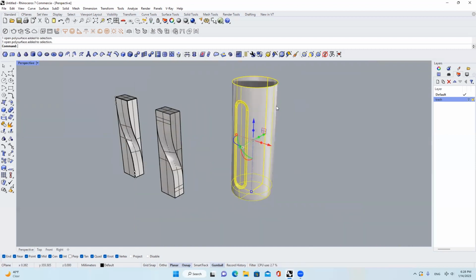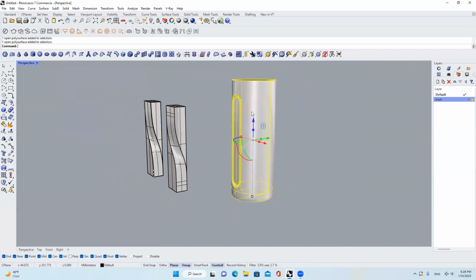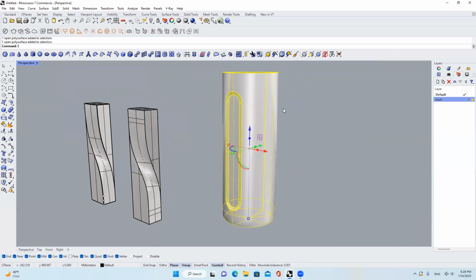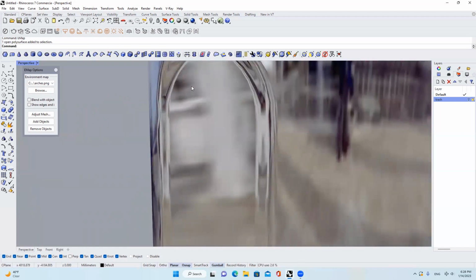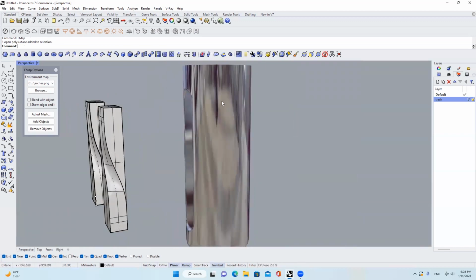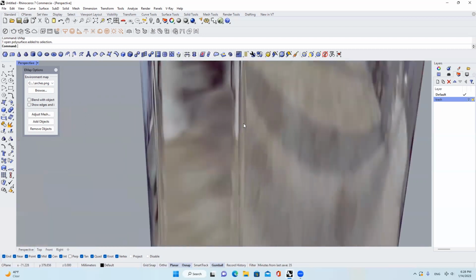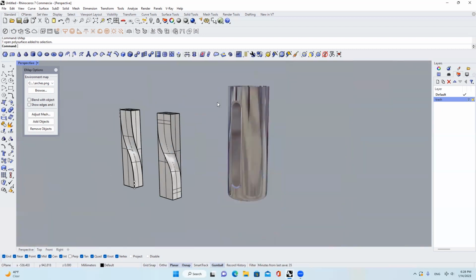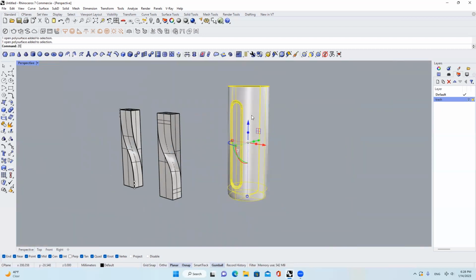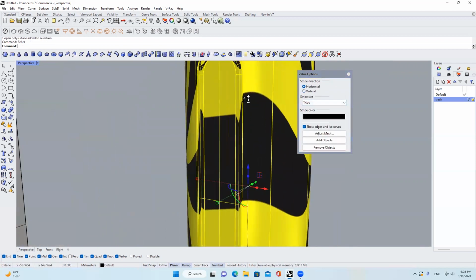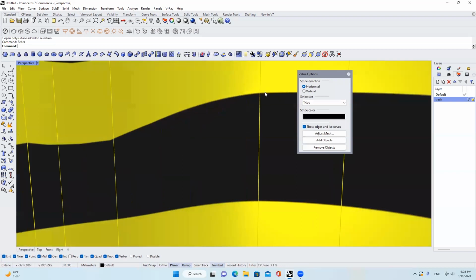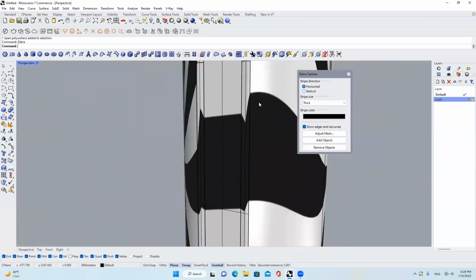Next thing I'm gonna do is I'm gonna draw this kind of water bottle. Again, let's use EMAP. We can zoom in and see that there's this flat surface on this cylinder shape, and the connection in between is actually very smooth. We can check it by using zebra. Okay, horizontal, and we zoom in, we can see that the continuity has been preserved in between surfaces.